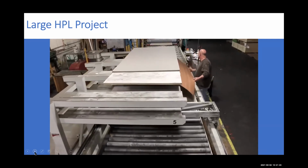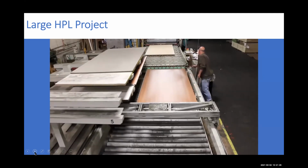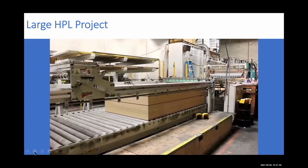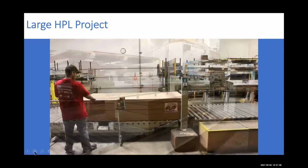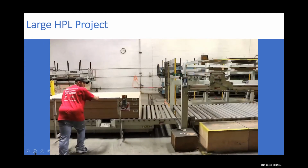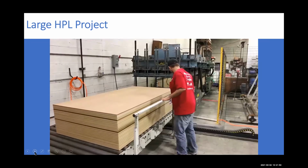And brings over the other sheet on top. So you can see he's got the laminate on each side of the substrate, and that means that the panel is going to be balanced. It's really important that the laminate on each side is the same thickness, otherwise they're going to pull at different rates, and you can result in a warped panel, which can delaminate or have stress cracks.